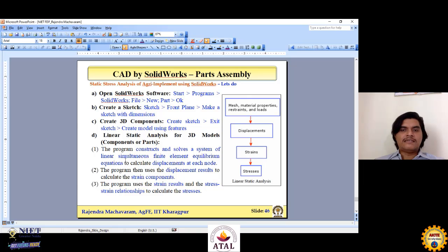By giving the boundary conditions and initial conditions, we also give the material properties, another important aspect. In SolidWorks, we can directly indicate the material of that particular object. After giving all these three, we have to mesh it. Meshing is the main aspect in the simulation part. It is the discretization of the entire complex structure into known elements. There are different three-dimensional or two-dimensional elements, like a cube or an 8-noded brick. These are finite element concepts we also need to consider.